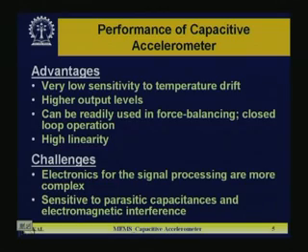But here, because capacitance change cannot be measured directly, you have to have an arrangement or interface electronics, so the change of capacitance is reflected as either change of voltage or change of frequency in the output, which you can further process for your application. That electronics is available, but it is not as simple as for the piezoresistive accelerometer.